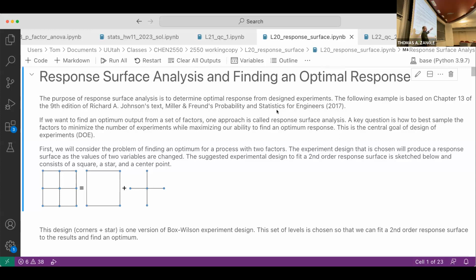The second is that real measurements are noisy, and that noise may confound your ability to determine where the optimum is. So even if you make a lot of measurements to cover this space, more than these 4, if your measurements are noisy, you may get an incorrect idea of exactly where the optimum is.